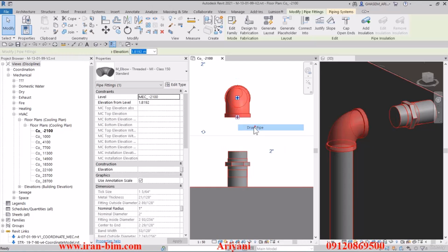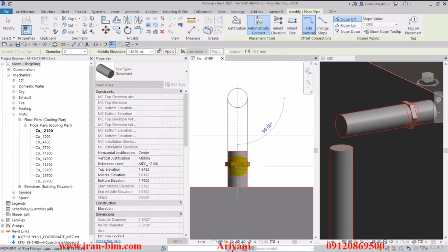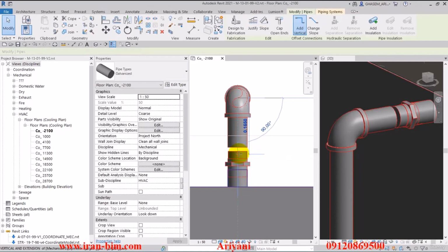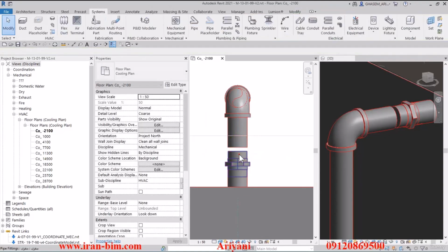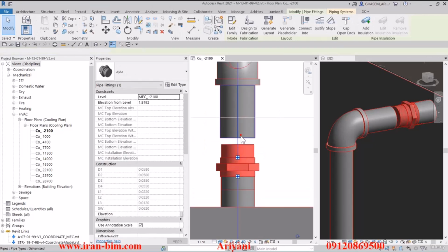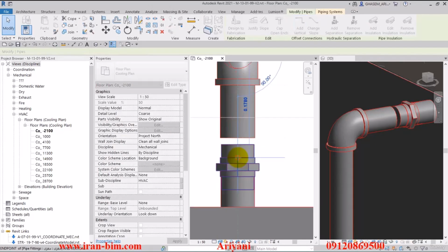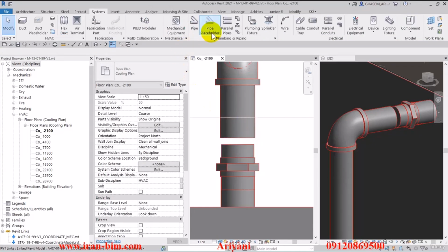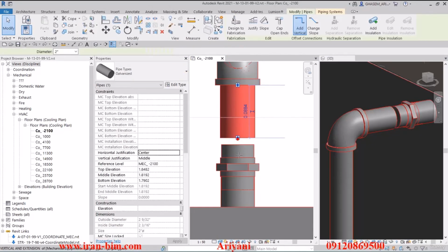Right click and select the draw pipe option and bring the pipe all the way down to the piece down here. Now we haven't connected them yet, we'll have to find the connection point first. It's right here. So I'll grab the pipe and bring it all the way down here. The reason that this gets deleted is because it hasn't been specified in the settings of this pipe. Now that's fine for now, it's no big deal.